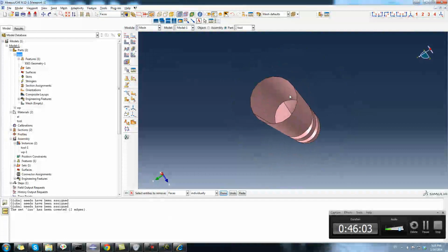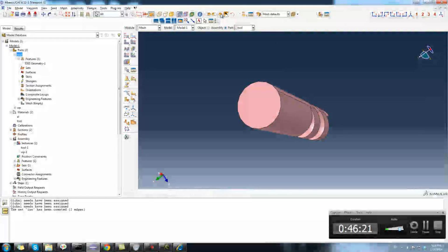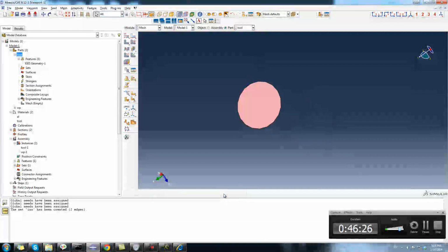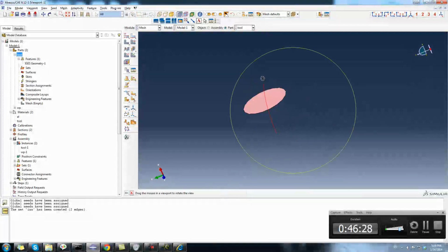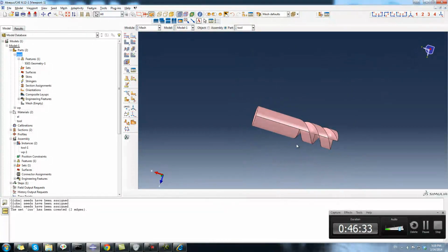As I told you earlier, if you export, it may export only the surface. In Pro Engineer you saw only surface, not solid. I think you export only the surface. Yeah. So this is a problem. And if you want to take this back, click here, it will come. And if you click it, it will remain this and others will be deleted. Like this will be here. Okay, click here, it will come. So this is the problem. You have to take solid. Okay, so I'm crossing it.